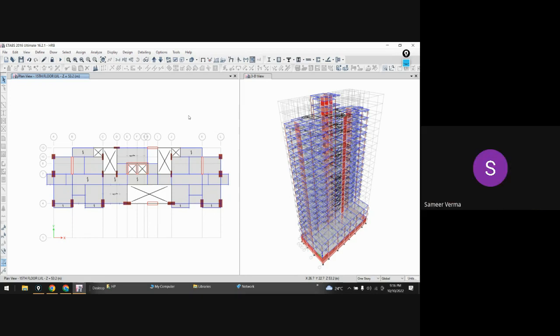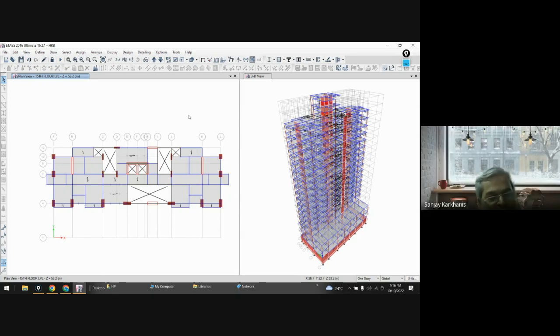Yes, sir. So the same thing happens with the building. The extra energy that has been given as input to the building cannot be sustained without getting excited, and that excitement we are training with our design. We are saying that, okay, if you get excited, get that energy dissipated either in translation in the x direction or translation in the y direction, but don't dissipate the energy by rotating about the vertical axis, so that you will not collapse, right?